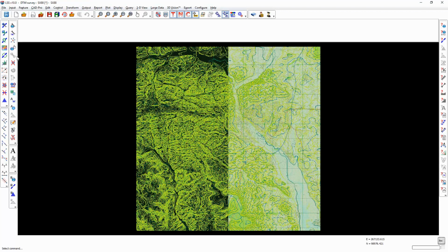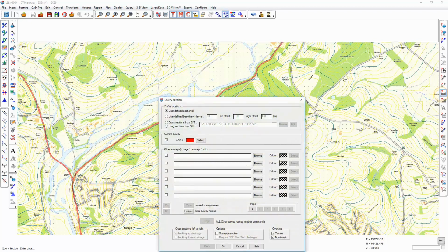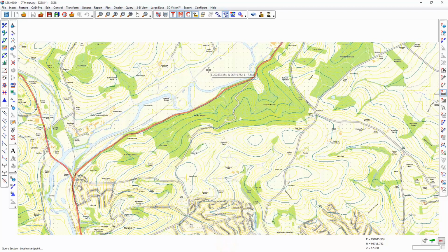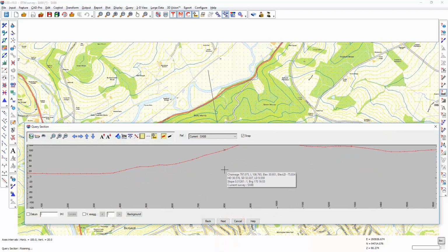And if we zoom in on a certain part of that, what we now have is a gridded data set producing a bald earth DTM model, and by bald earth we mean the terrain model without any objects on it such as woodland, buildings, etc. If we draw a long section through it, we will see that bald earth DTM.